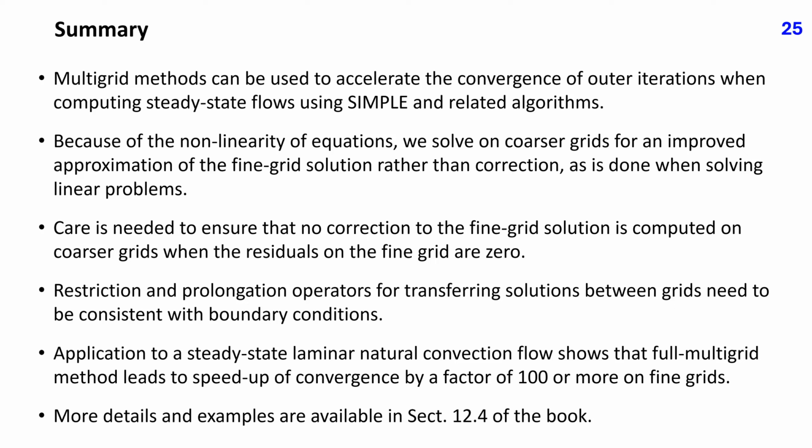Let me summarize the main takeaways from this lecture. Multigrid methods can be used to accelerate the convergence of outer iterations when computing steady-state flows using SIMPLE and related algorithms. Because of the nonlinearity of equations, we solve on coarser grids for an improved approximation of the fine grid solution rather than correction, as is done when solving linear problems. Care is needed to ensure that no correction to the fine grid solution is computed on coarser grids when the residuals on the fine grid are 0.